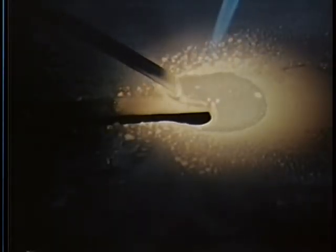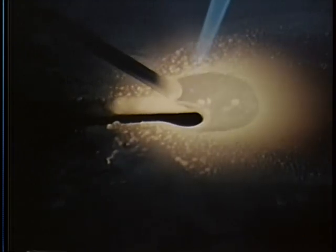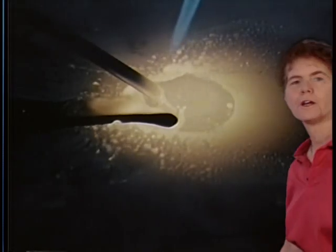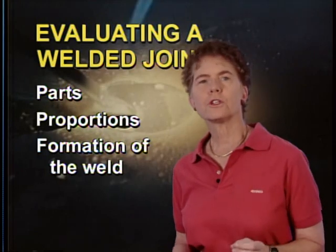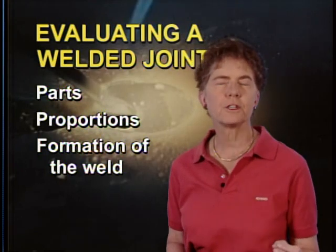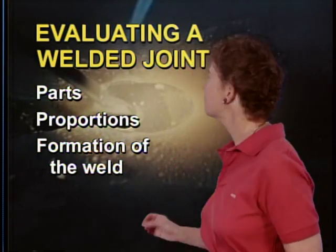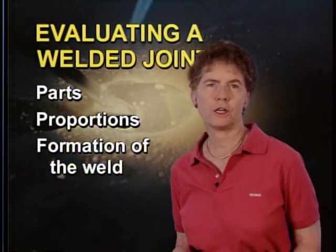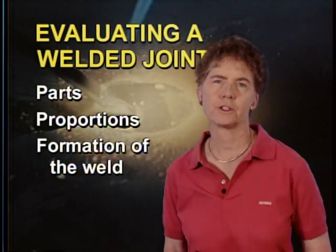Now, as a mechanic, what in general do you look at when you're examining and evaluating a welded joint in an aircraft part? Well, first of all, you want to start with the big picture. And to do that, you should be familiar with the joined parts, the proportions of the weld depth to the material thickness, and the formation of the weld. And of course, in your examination, you'd want to check some details.